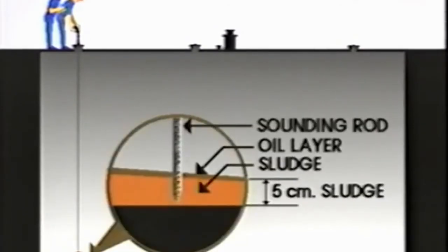When the cargo is discharged, all tanks will be searched for remaining cargo on board, ROB. The tanks will be dipped only in the aft part. The special sounding rod fitted to the MMC is used. Too often there is discussion of ROB even when the indication on the sounding rod is less than an inch or a few centimetres. Most likely there is unpumpable mud or sediment in the end of the tank.